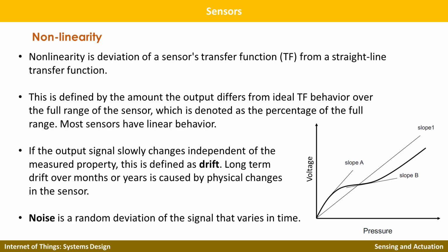Those kinds of drifts could be addressed in the software layer by looking at the other sensors and doing some kind of software layer calibration, adjusting the incoming values. But again, it's a trade-off between when you want to change the hardware, or physically deploy or replace the sensors, versus changing the values and adjusting to the drift.